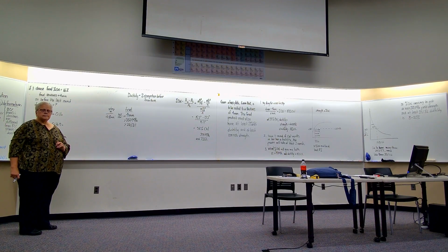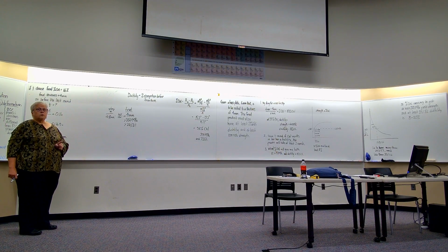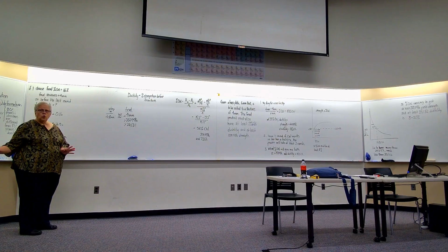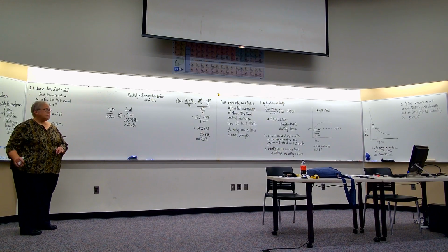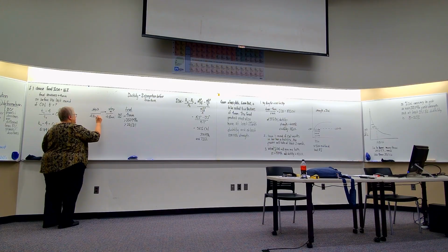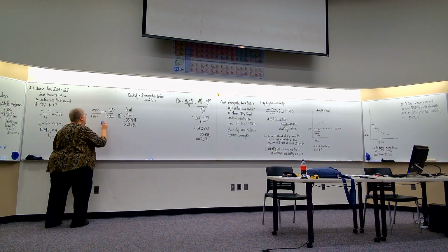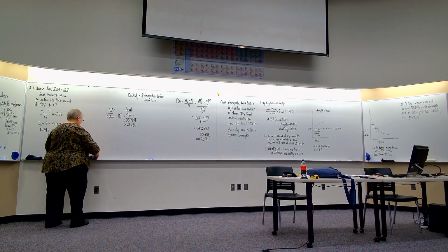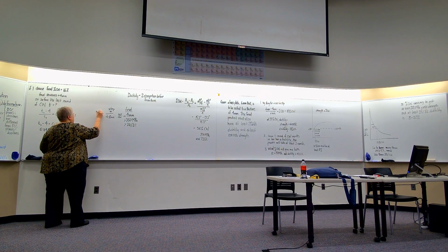Before I do that cold work, there has to be no cold work in the sample. And so step 3 is the same dimension. Before I start that step, I need to anneal.